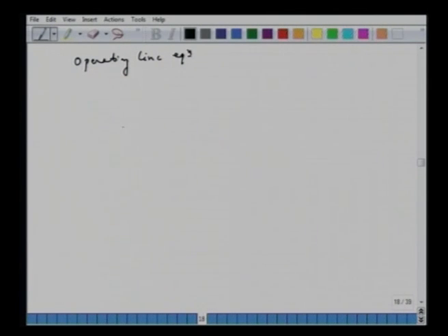So for the top column we have a general expression: yn+1 = (R/(R+1)) xn + xt/(R+1). If we choose the nth plate here, the vapor which arrives here has composition yn+1, and the liquid which leaves the nth plate has composition xn. So that's what the operating line does.